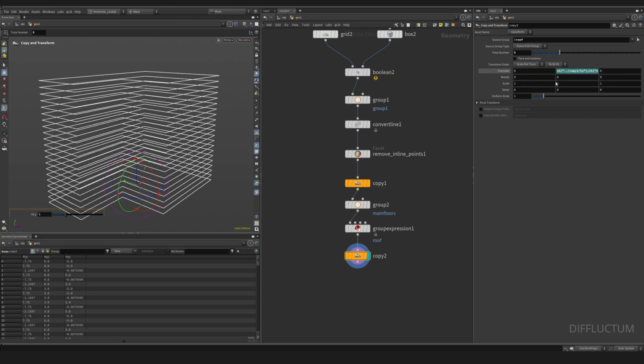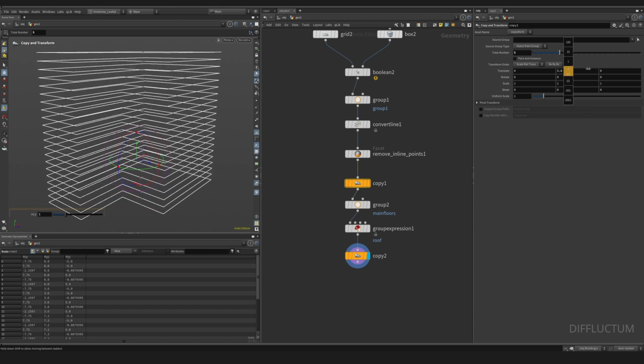By left mouse clicking into the parameter, we can switch between the expression referencing the parameters and the actual value it outputs. This allows us to keep everything connected, meaning when we change the amount of floors or the floor height, it updates automatically.